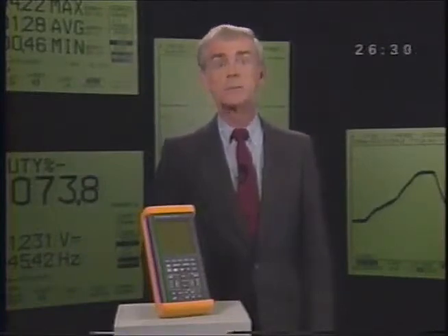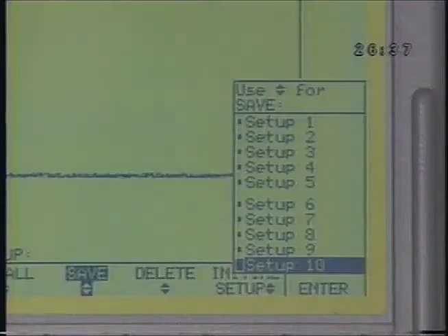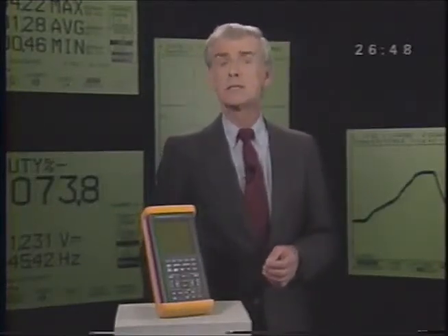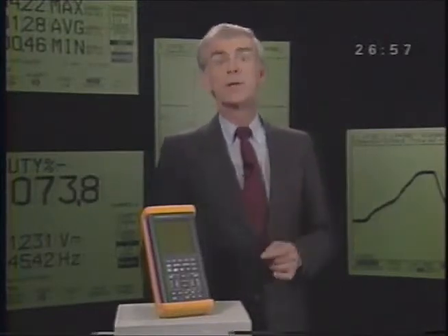To display any waveform, you must make a set of adjustments, including voltage scale, time base, trigger level, and so on. Each specific configuration is called a setup. One of Scopemeter's features is its ability to save and recall up to 10 setups. The setup for this waveform is similar to the setup for all AC generating sensors operating at slow speeds, including distributor pickups, crank sensors, and anti-lock brake system wheel sensors. Save this setup in memory number 1.